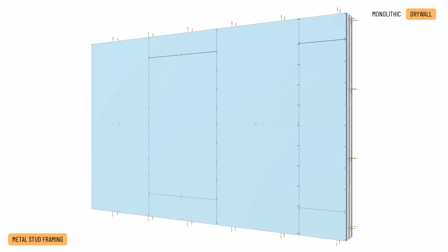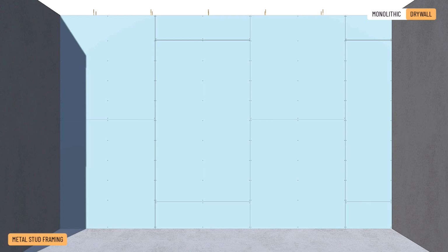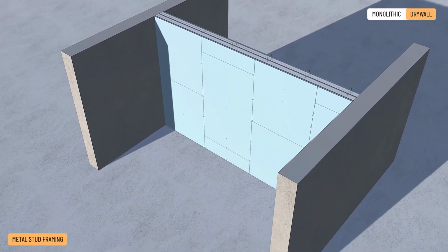This time, the boards are also spaced at the sides by 6 to 8 mm at the bottom and 2 to 3 mm at other places. The gaps are filled with a flexible filler such as silicone. Finally, the surface treatment is applied. The joints and bolt heads are filled with putty applied with a trowel, while reinforcing strips are placed along the joint. Then the perfect flat surface is achieved by sanding. If necessary, the puttying is carried out in several stages.